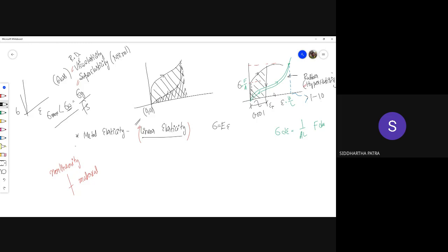If you're trying to model elastoplasticity, hyperelasticity, superelasticity, viscoplasticity, or any other model, even a model which approximates plasticity like elastic perfectly plastic, that is also a nonlinear material model.